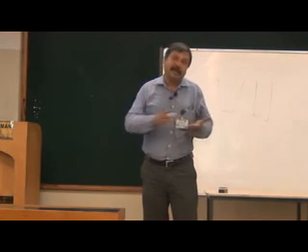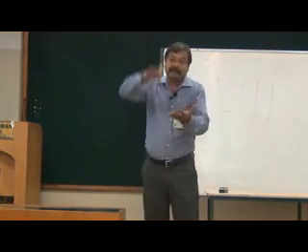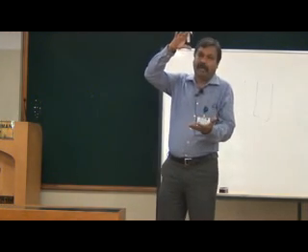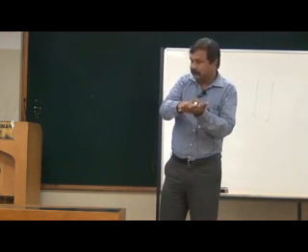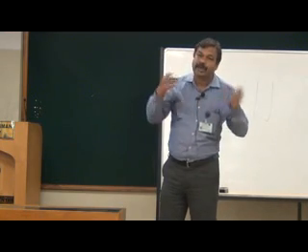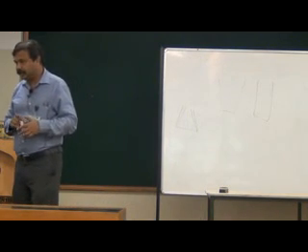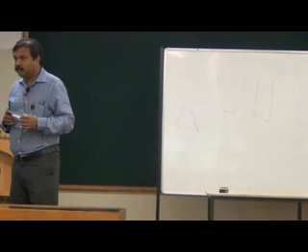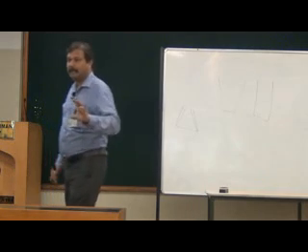Now the raw material is a metallic sheet. Now what you have is two dies. This is again a metal forming process. You have two dies which come and hit the raw material. The raw material is shaped to the required shape and dimensions. So this is one type of metal forming operation.